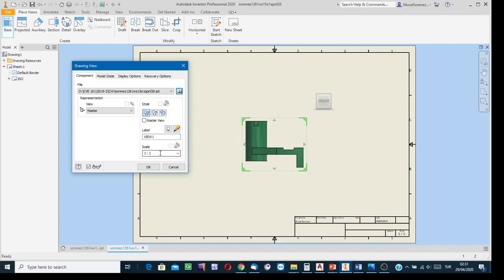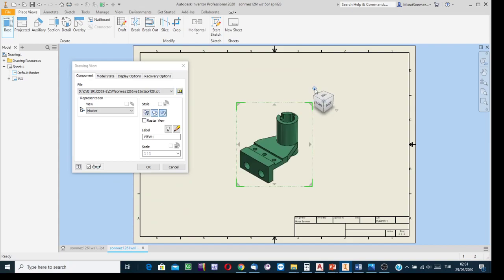Scale factor 1:1 I think is suitable. Orientation of the body, to be able to allow yourself to see the model as you fixed as it is home positioning. Click on the cutter symbol, and then while observing the simulation as you selected in home positioning, you can much more easily say which side you selected, the front side of the object, then see which surface of the cube is parallel to that side.